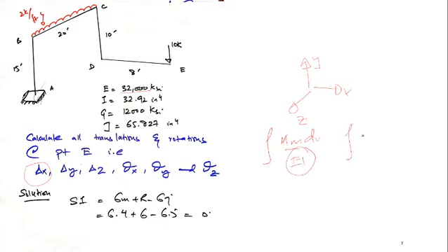However, if you have to use the torsion, you have to use the formula with GJ. Now this is the torsional rigidity, and this is the modulus of rigidity. Because we are going to construct the moment tables, there would be some torsions there. So that's why we have to use this formula. It may be used.